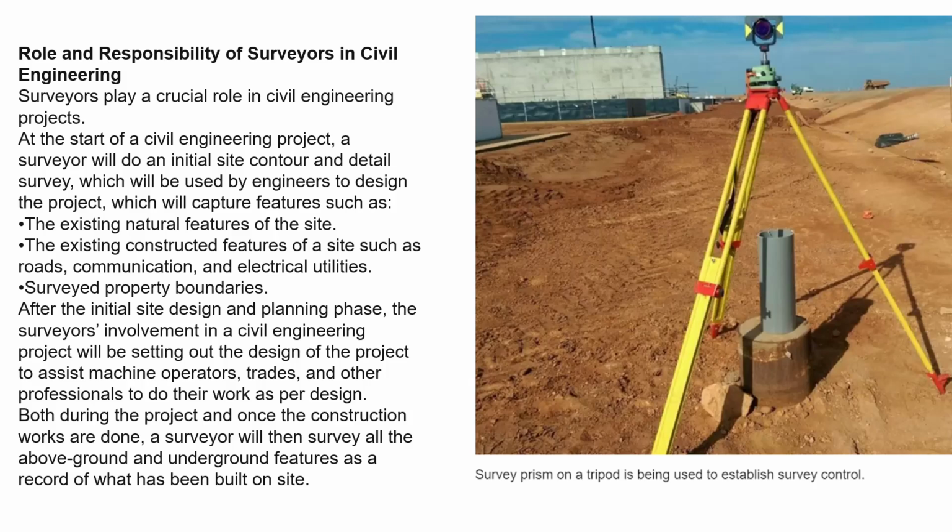At the start of every civil engineering project, a surveyor will do an initial site contour and detail survey which will be used by engineers to design the project, which will capture features such as the existing natural features of the site, the existing constructed features of a site such as roads, communications, and electrical utilities.